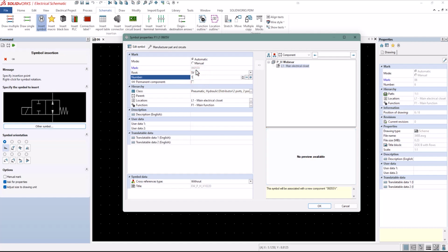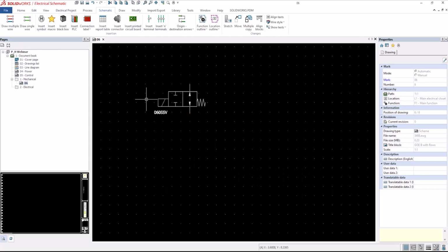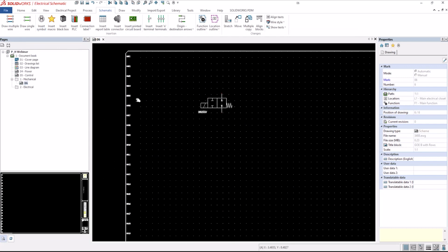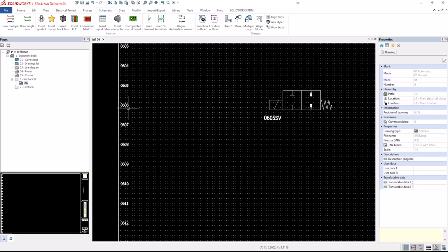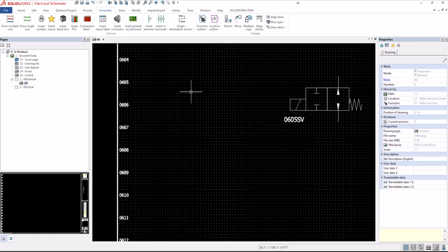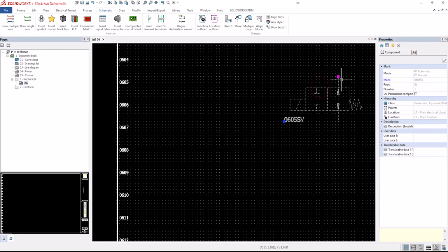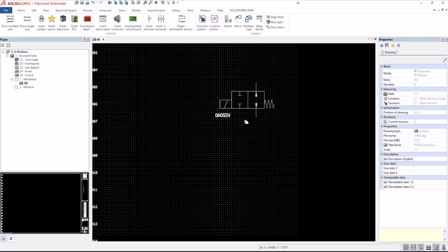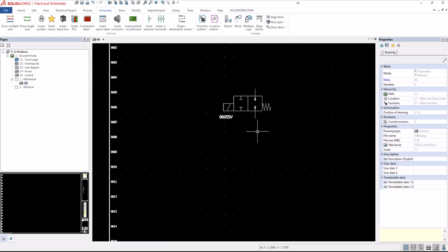So when I make that adjustment, it does adjust this. I have a numbering scheme for this project so that it is using a sheet number row number. So notice that I place this on 605 here is where this is being placed from this pink dot. That is where it's coming up with this number. You can set up a formula for anything here.